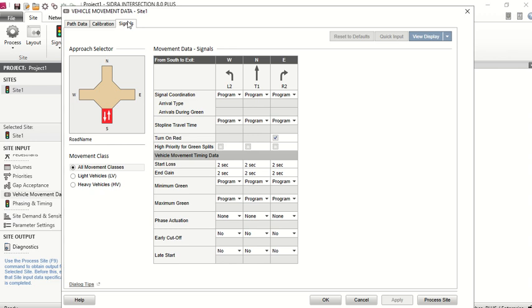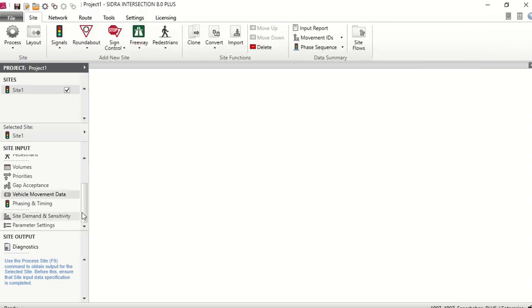We discussed it, semi-actuated, coordinated signals. What are coordinated signals? All the greens in the sequence that flows. Yes, it's a sequence of signals which are programmed together to give the drivers continuous green. These are coordinated signals. So if you have coordination, you can put the values over here. Arrival type, we have seen the table for arrival type and these things, but if you just put the spacings, the program can calculate the arrival type and everything for you.